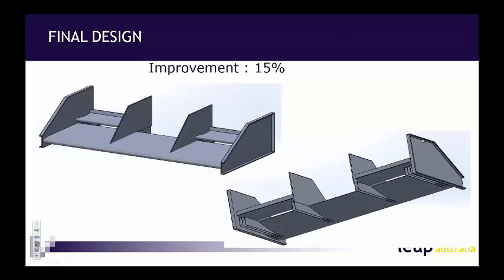This was just focused on the front wing. You can see here where we use a 2D kind of design of experiments due to its quick runtime to figure out roughly where I should start. We then looked at the 3D cases. We did some what-if studies. What if I had a bigger end plate? What if I had a flap? What if I had some strakes? And we can also take that a step forward. We can do some joint, so we can use the software to change the actual shape.